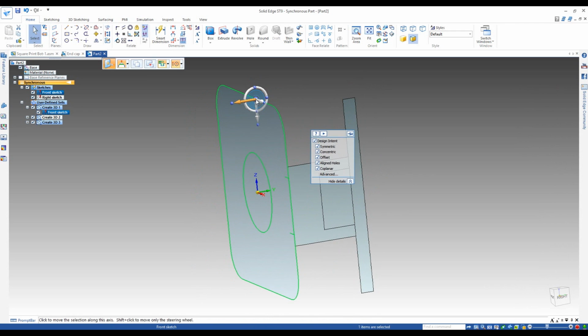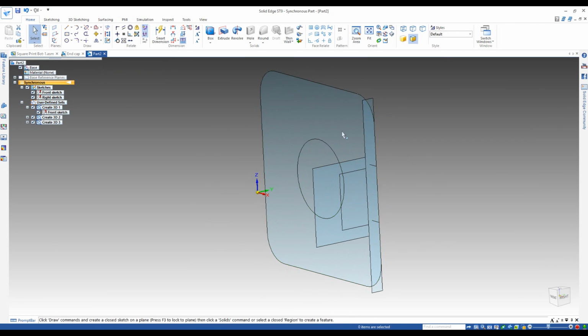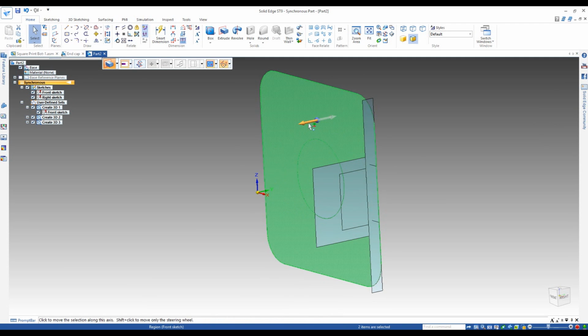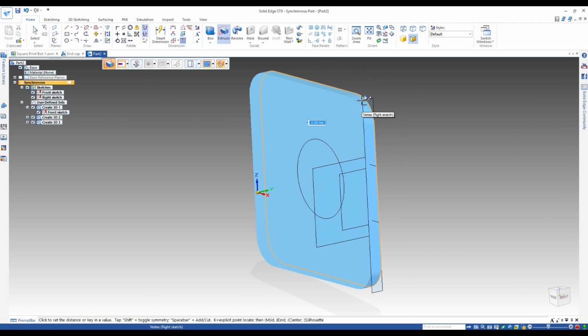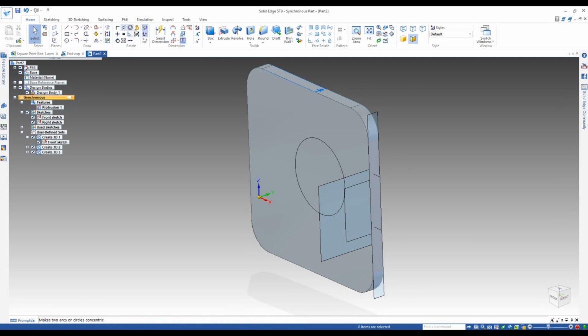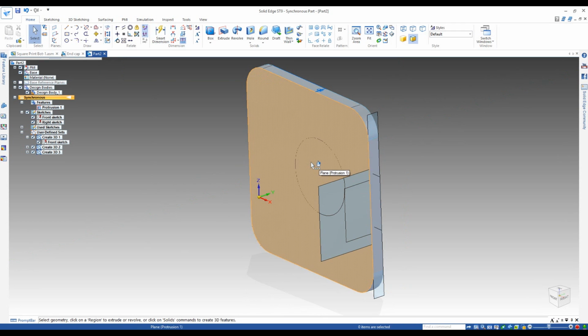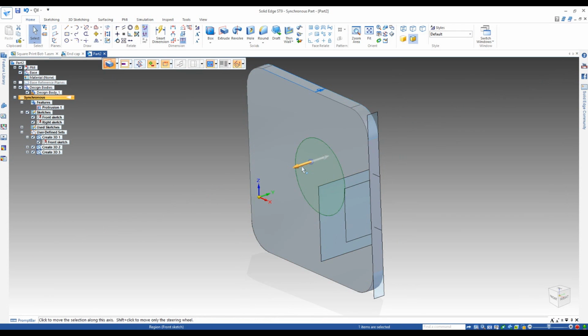And then what I'm going to use is the Synchronous Technology side of things, just simply to add material onto my body. Do a quick dimension check, 30mm, that's scaled correctly. Just need to pull this cylinder out. I can either add or subtract, and I can just tap the spacebar to toggle those as well, just to make it nice and quick.